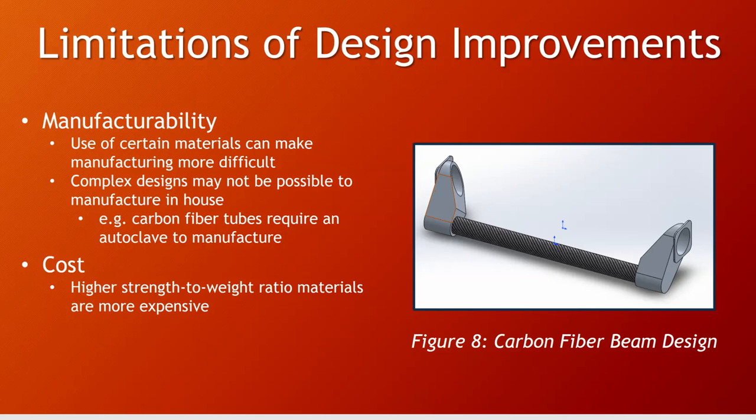So any metal other than steel will prove difficult to manufacture given the team's current abilities. Any sort of composites work would also have a large learning curve, and also the team does not have all of the necessary equipment to properly make structural carbon fiber parts. As with all engineering, cost is of utmost concern. If at any point the suspension becomes damaged, the more expensive it is to produce, the more expensive it will be to repair.